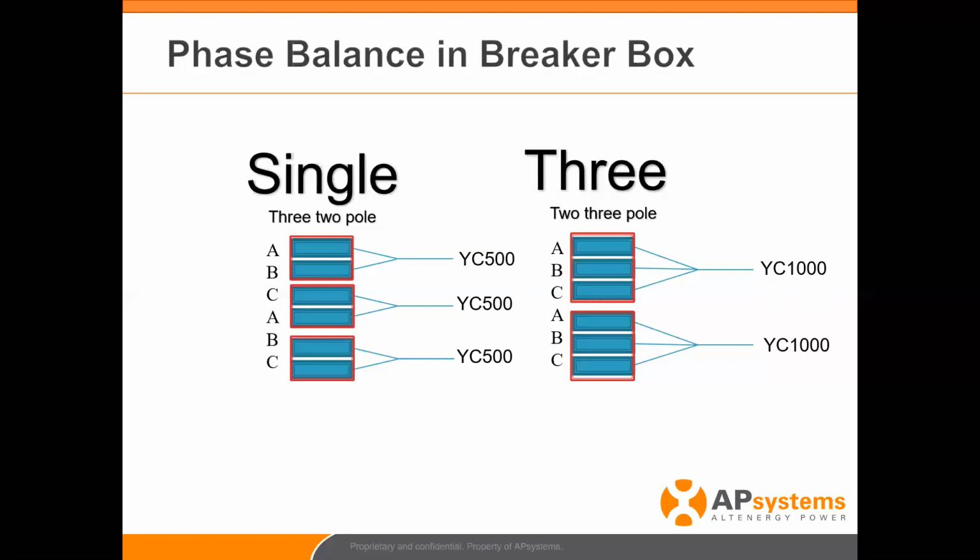One thing to note, we had a customer just recently, probably like a month ago, ask about Jinko 400s. They said, "Oh, Chris, I've got a Jinko 400 I want to use with your QS1, but I think it's too big because you have a 300 watt max AC output per channel." And I said, well, not so fast. Let's take a look at the spec sheet. The STC, or standard test condition, for the module was a 400 watt Jinko.